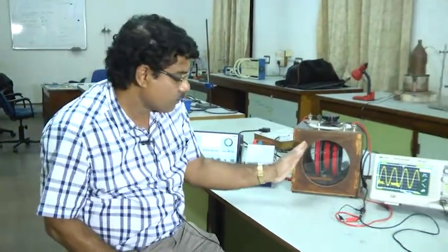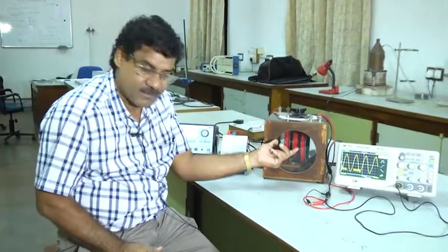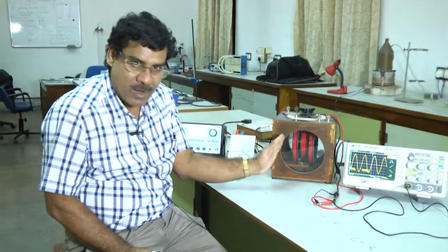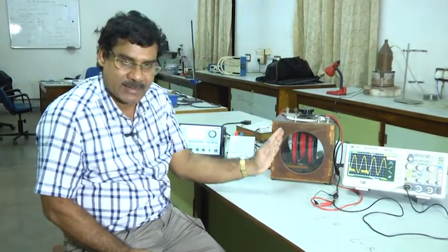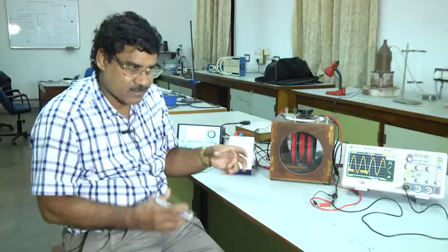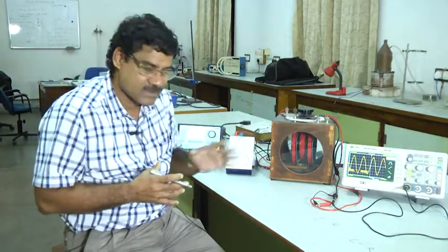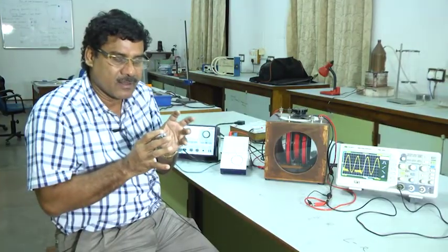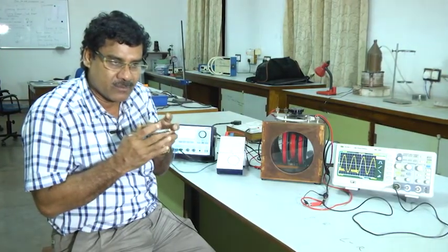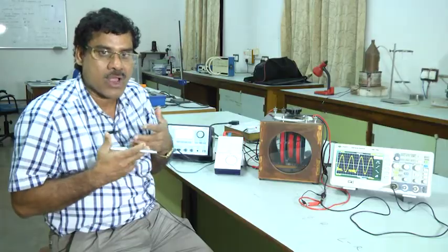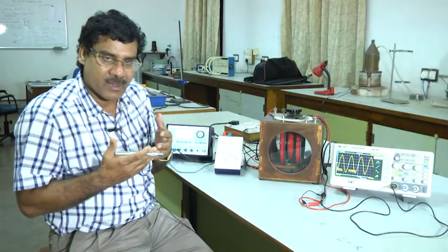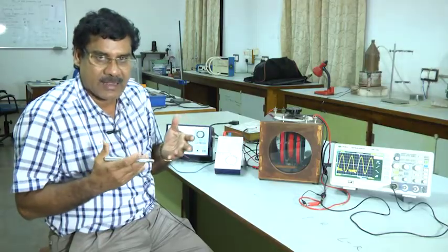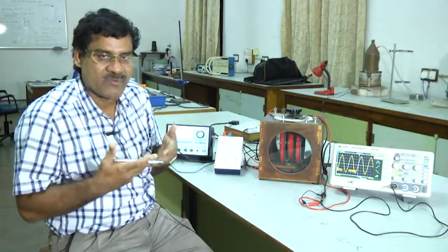Again, do not get confused by these 3 coils. Effectively one primary coil and one secondary coil is enough to study, but the signal will be weaker, because the flux passing through the secondary coil will be smaller if the magnetic field is weaker. If the field is stronger, obviously the flux will be higher and the induced EMF will be higher.